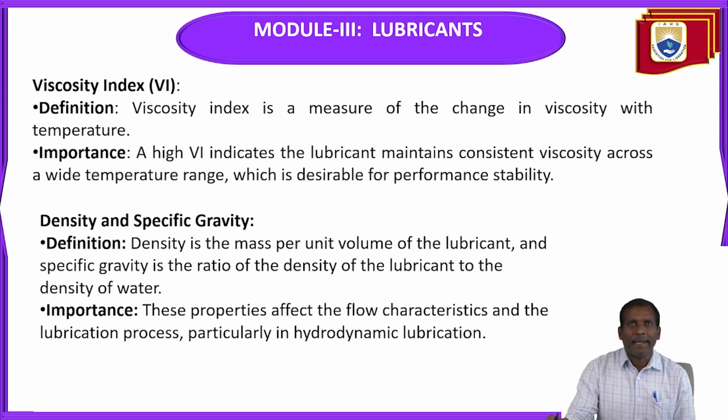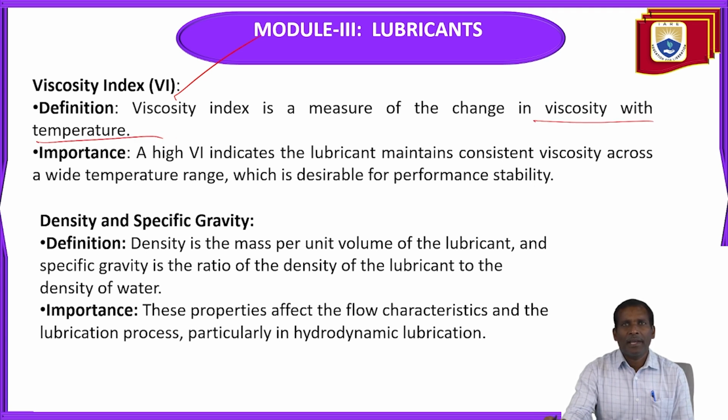Next, viscosity index, which you can write as VI. The definition: viscosity index is a measure of the change in viscosity with temperature. The importance is that a high viscosity index indicates the lubricant maintains consistent viscosity across a wide temperature range, which is desirable for performance stability.